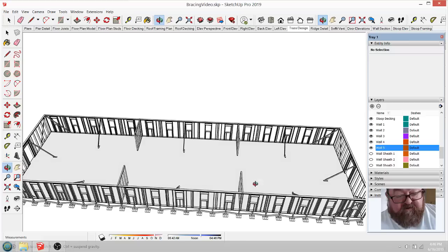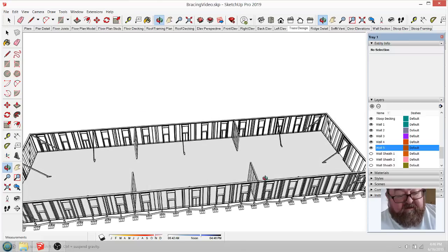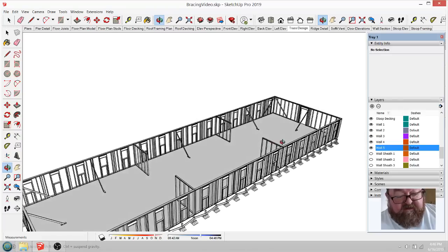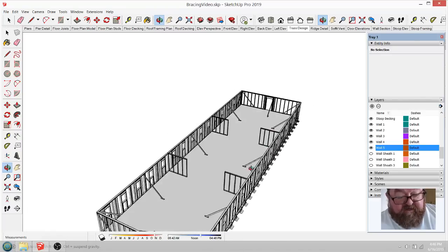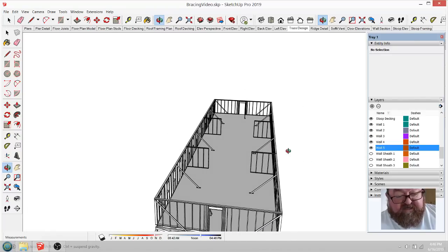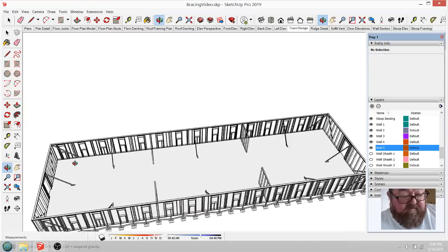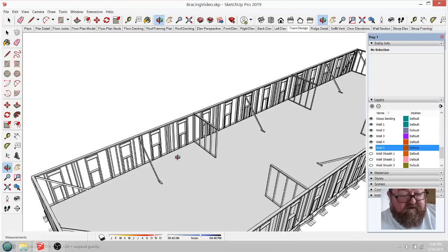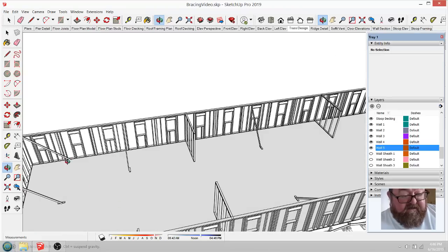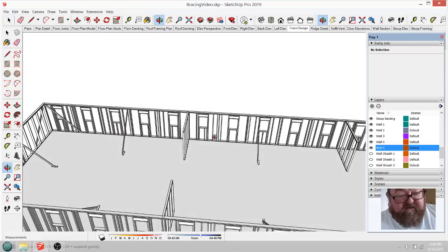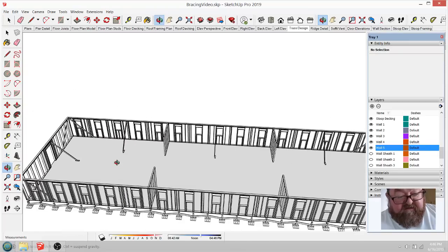So I'm just showing them at thirds here, and again, these windows aren't really here. Now, what you can do is incorporate these shear walls into your design. Say you have bunks in this building, and you count out the spacing you need, the number of bunks, and you put these walls in between 2 sets of bunks, that kind of thing.